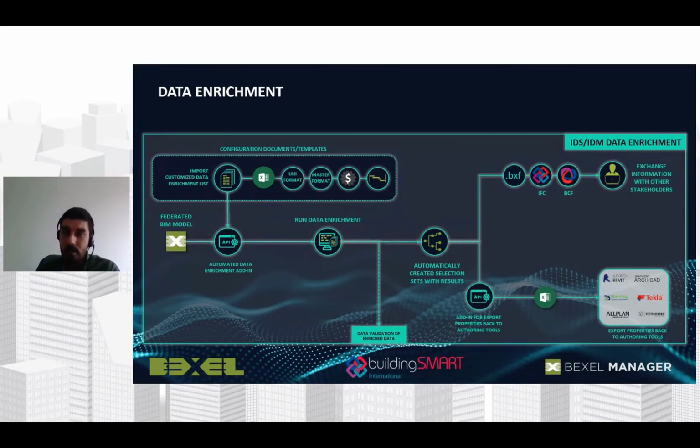In order to achieve this in Bexel Manager, you can use an open API system, and the user is practically able to specify their template and keep it on a local computer disk or in the cloud. Whenever they start a new project and receive a new model, they can just download and import these specific rules for enriching the data and adding new data, and in this way classify existing model elements into a certain classification system.